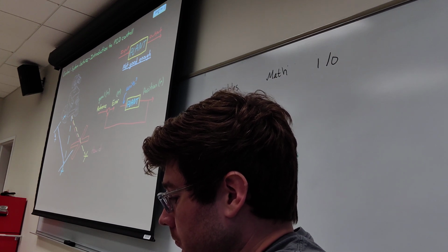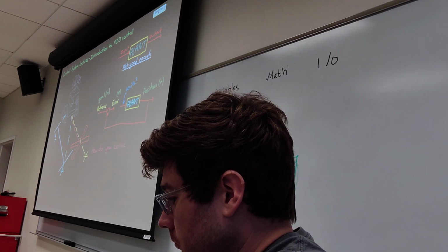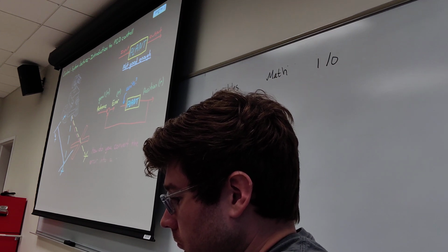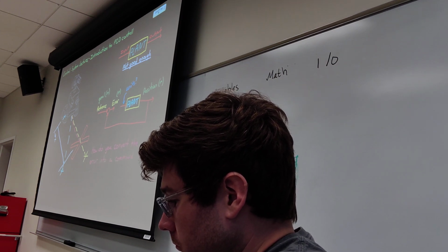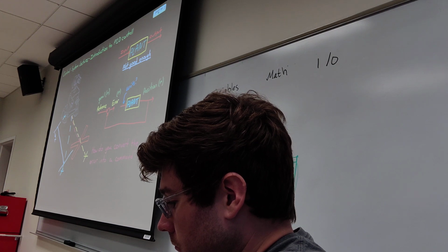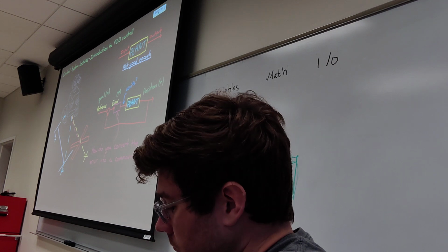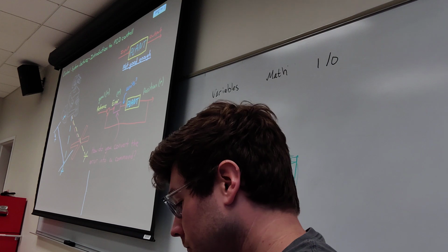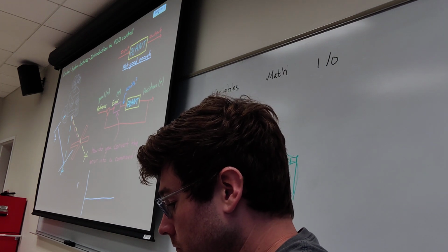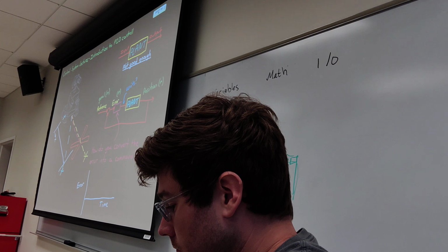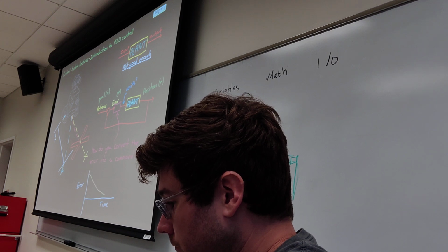And in addition to just changing the units, the error needs to be adjusted in such a way that the input into the robot causes it to eventually reach the red X. And this is exactly what a controller does. It takes the error signal and converts it into a command that is then sent into the plant. And one of the goals of a control engineer is to design this controller so that as time progresses, the error, or the difference between the current location and the goal, is driven to zero.